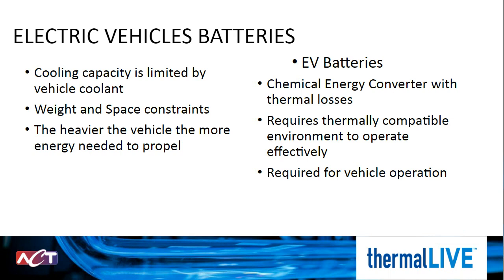Environmental temperatures can affect the speed at which that reaction occurs. It'll slow it in cooler temperatures and increase it in warmer temperatures. It also can increase the resistivity in the conductors. So higher resistivity means higher energy losses in the form of heat.